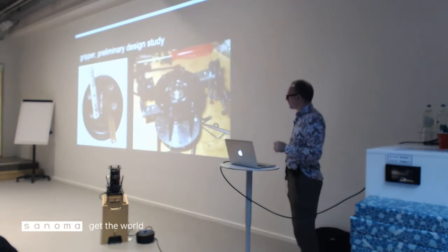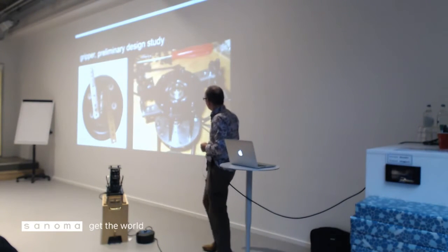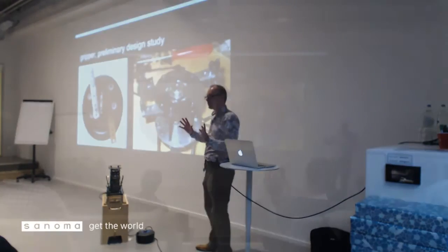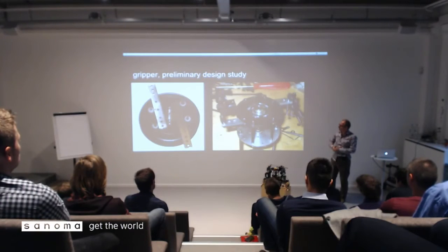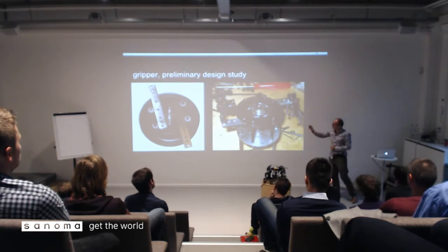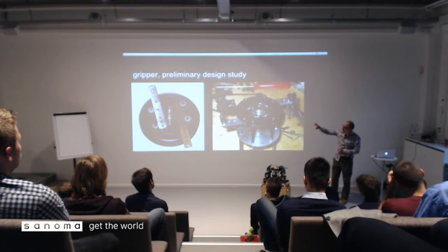the different components of the machine are, well, of course, the grippers itself. You have several types of grippers, but one of them is a so-called toothed gear rack gripper. In the center you see a small gear, and it actually drives the gear racks.